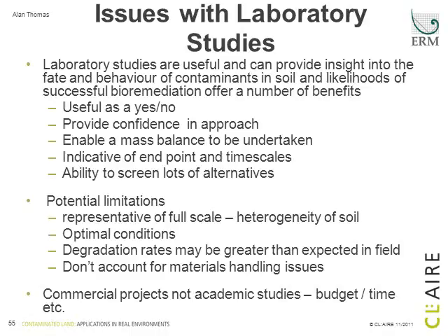There are, however, potential limitations as well. Clearly, there's a big question mark over how representative they are of the full scale, particularly when we see some of the heterogeneity in sites, as we've already discussed. These are very much optimal conditions. How are you going to replicate those within the field? That is a difficulty. What it may mean is that the degradation rates that we get in microcosms are greater than we'd expect in the field, and they don't account for materials handling and contaminant delivery issues in the field.